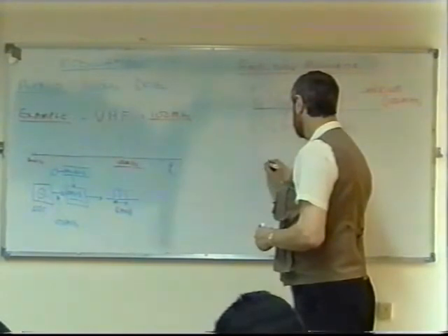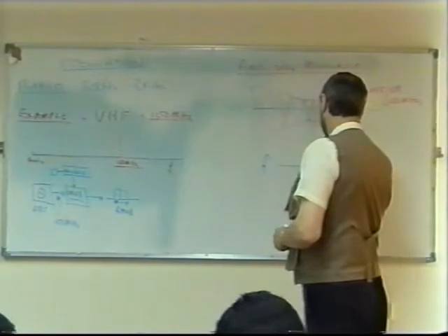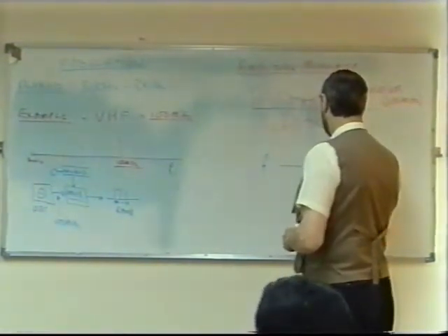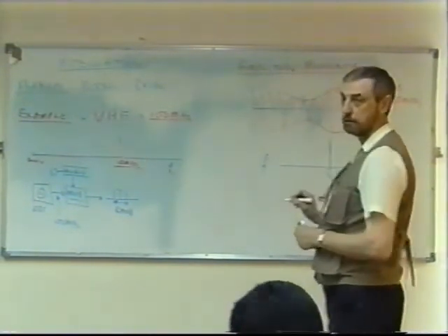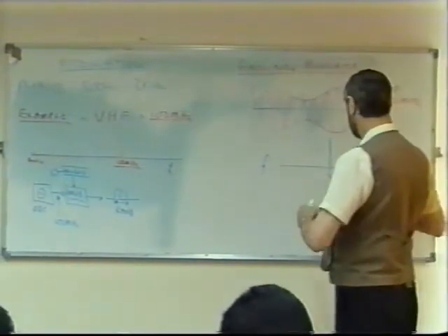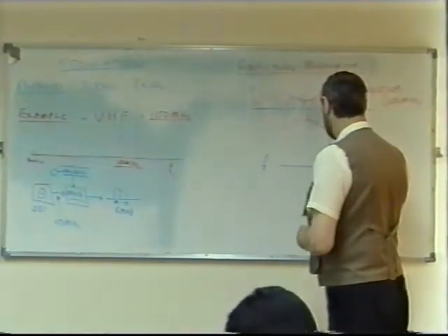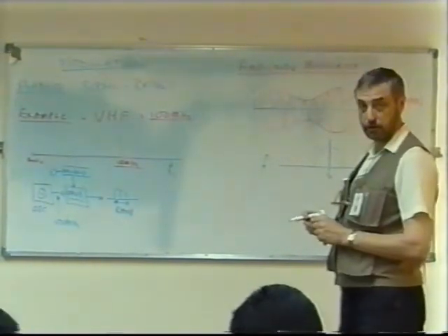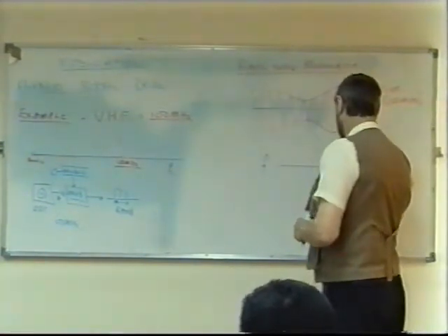And it can be shown that with amplitude modulation, if we have a look at this graph now, what we actually transmit from the antenna will be the carrier, which I'll call FC, in our case 100 megahertz, and there'll be some frequencies above FC up to a maximum, and some frequencies below FC. In other words, there's a band of frequencies we're going to transmit. Now, the next thing to decide is what these frequencies are going to be.